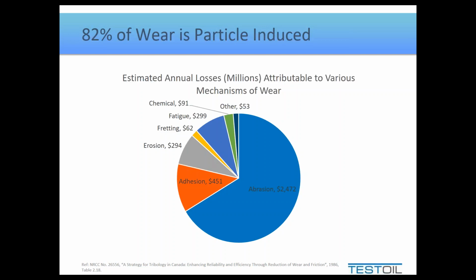That's the whole point of these two different studies, that most of the wear, whether you want to say it is more than 50% or you just want to say it's the single largest slice of the pie, most of the wear that we're looking at in terms of lubricated components is going to be attributed to some sort of particle contamination. So that's why we're so concerned about storage, handling, even the application of the lubricants, and then of course the conditioning, the filtration of the lubricants after they've been put into play.